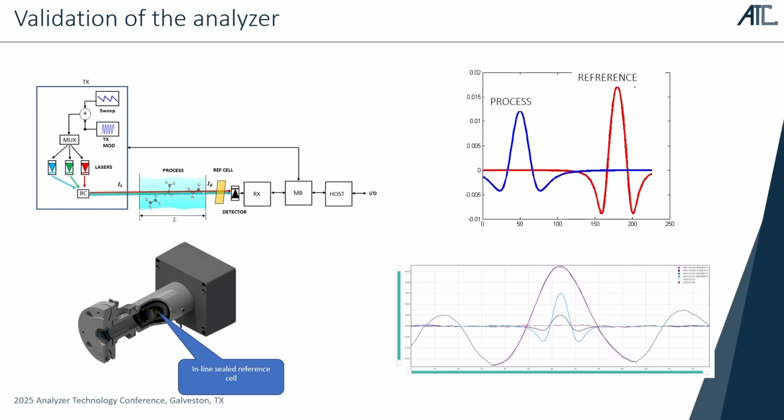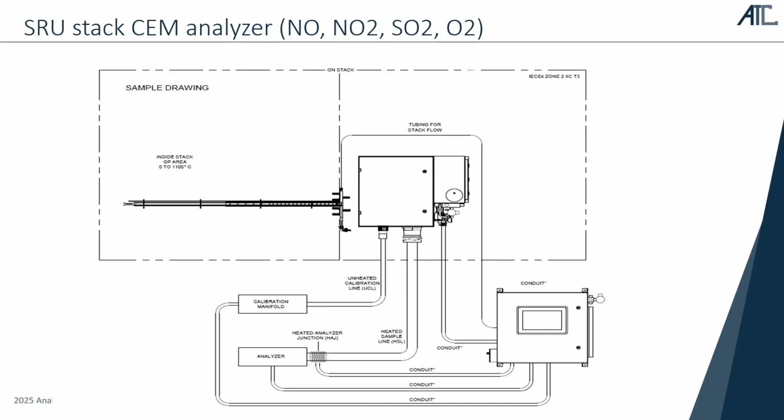Okay, so this was the information about our in situ analyzer. Now I would like to show more data about our extractive analyzer that we developed for sulfur recovery unit stack continuous emission monitoring. This was solely developed for the Middle East market, so we had the challenge to provide an ambient temperature rating for the analyzer of plus 60 degrees C. And this had to be done hot-wet because the sample had to be maintained hot.